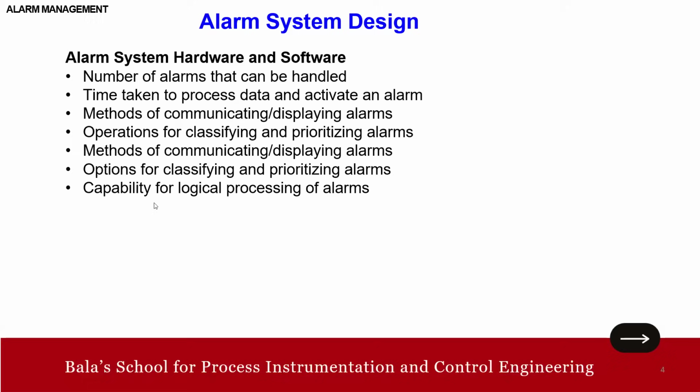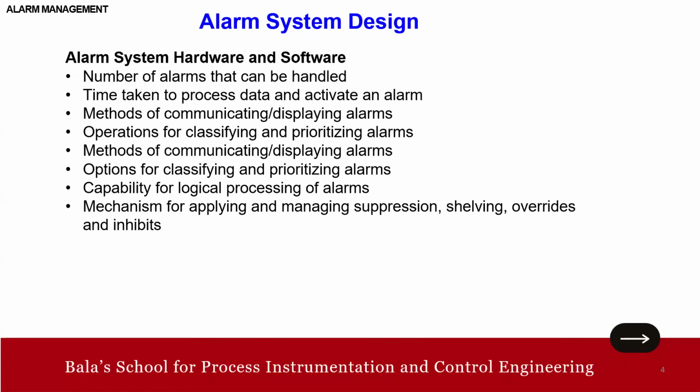Capability for logical processing of alarms, and also the mechanism for applying and managing suppression, shelving, overrides, and inhibits. We are going to talk about this also in the subsequent session. Then options for handling highly managed alarms.